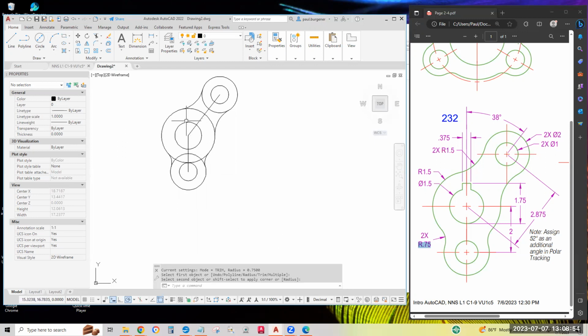Now, the keyway is always tricky for students. Machinists like the keyway to be dimensioned from the bottom of the hole, so a snap caliper or some tool will measure from the bottom of the hole to the top of the keyway. And that's far easier to measure than from the sharp edge near the top of the circle to the top of the keyway. Let's see, the dimension from the bottom of the hole to the top of the keyway is 1.75.